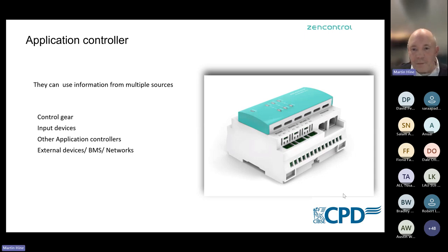Obviously, with sensor integration, DALI 2 also supports various sensors, including occupancy and daylight sensors for monitoring the light levels to comply with constant light control for lighting close to windows or south-facing windows where there are increased light levels. The lighting controls can use the sensors to reduce the light levels of the fittings near the windows.